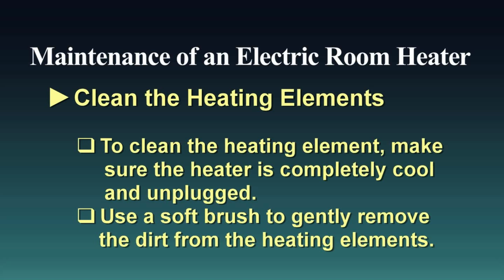Over time, the heating elements may accumulate dust and debris which can hinder their performance. To clean them, first make sure the heater is completely cool and unplugged. Then use a soft brush or a vacuum cleaner with a brush attachment to gently remove the dirt from the heating elements. Avoid applying excessive force or using sharp objects that could damage the elements.